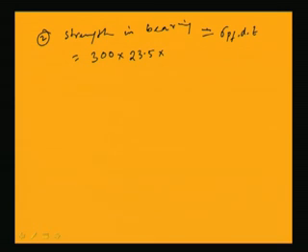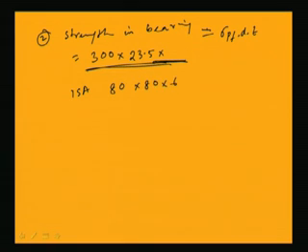Okay. So, for thickness, the plate thickness we have to make, sorry, the member thickness. So, let us assume a member. Before that, of course, we have to assume a member, say ISA 80 into 80 into 6, let us assume this, because the required area was given as 571 millimeter.